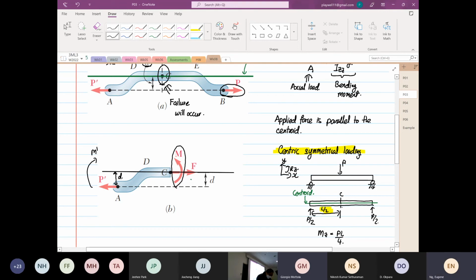And then we have an axial load, axial force in the x direction, P prime. We have a reaction that is our F. Again, Newton's third law, action equal to reaction, same in magnitude, different in what? Direction. Okay. So now I'm going to sketch for you how the normal stress distribution looks now.